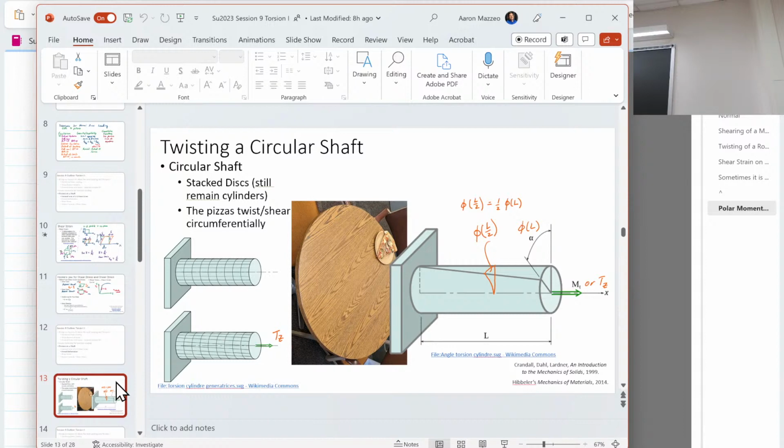maybe you just plug in the material property wrong, right? Or your units are wrong, right? Or your boundary conditions are wrong, or your force, right? There are all these things that can be wrong, or you don't have enough elements, right? So you have too few elements, and so it converges, but it converges to something that's not accurate. So you have to add more elements. So these are kind of the basic techniques that we're going to cover here, and that you can take and then apply when you do more complex work.